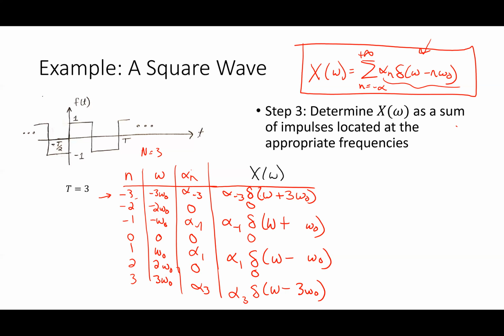The Fourier transform, this guy is now a complex function of frequency, right? And what's the meaning of that? What's that mean if I want to actually graph it? I can plot a function by just having the output value on the y-axis and the input value on the x-axis. Can't do that here, can I? What do I have to do if it's a complex function? Got to do the magnitude on one graph, angle on another graph, right? So this guy becomes two graphs.